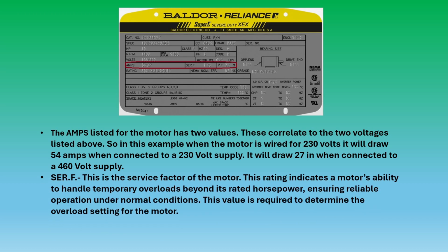Service factor. This is the service factor of the motor. This rating indicates the motor's ability to handle temporary overloads beyond its rated horsepower, ensuring reliable operation under normal conditions. This value is required to determine the overload setting for the motor.